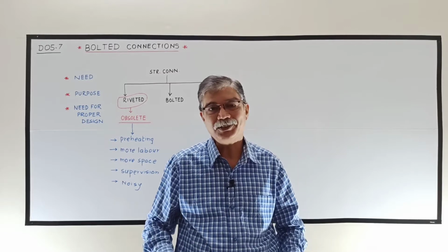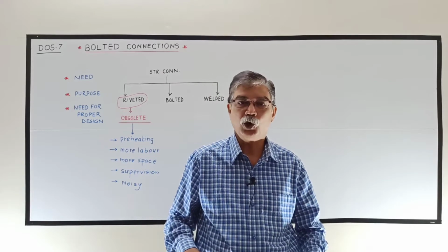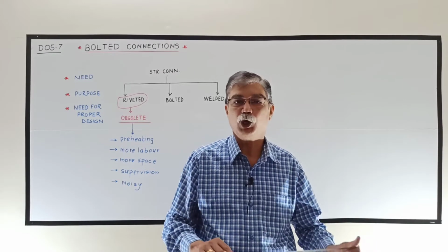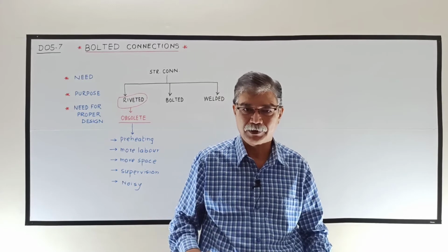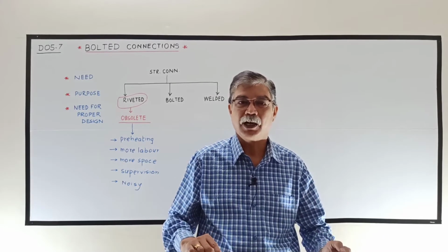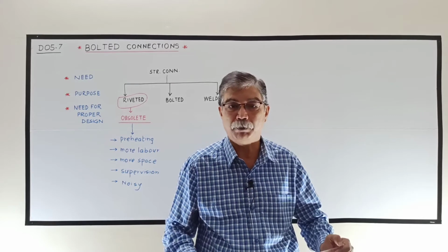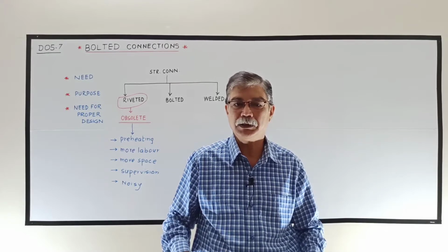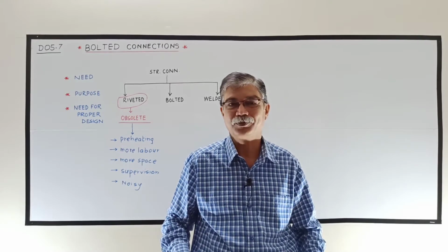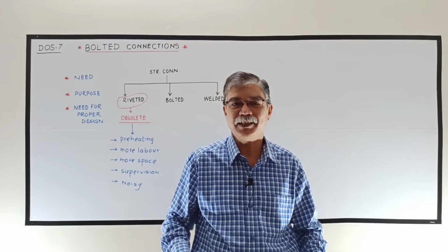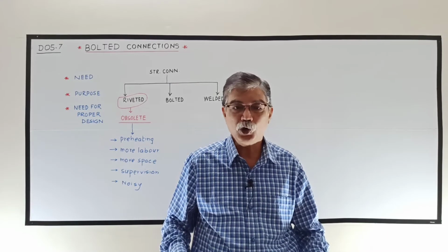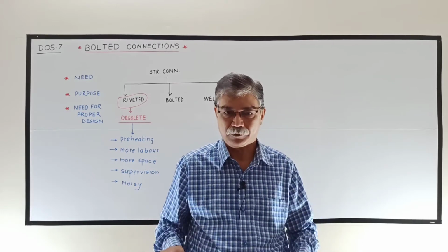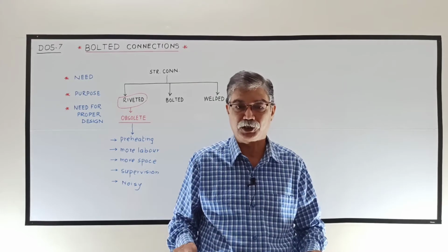Through the connections, the forces and moments are transferred from one member to another member. These forces are transferred up to the foundation. So this is the main purpose of the connections, to facilitate the flow of forces and moments from one member to another. So this is the purpose, this is the function of connections.